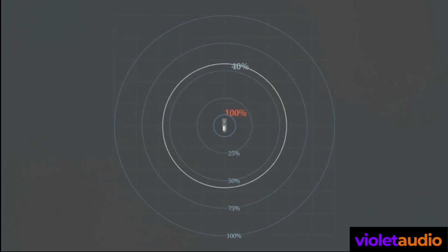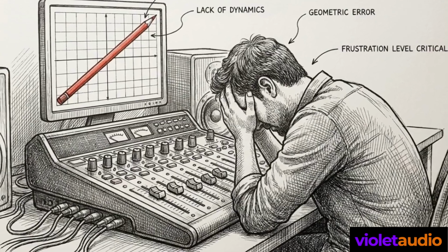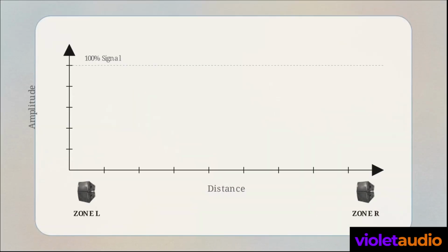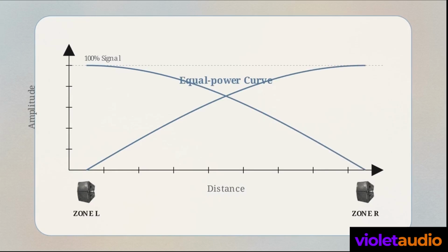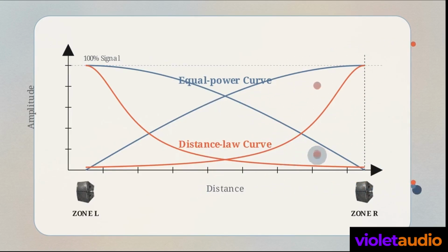Applying simple linear panning across a multi-zone immersive rig fails in practice. The acoustic transitions near boundary edges become too abrupt, destroying the illusion of physical space. Spatia relies on 2 spatial rendering formulas for signal amplitude. The equal power calculation ensures perceived musical loudness stays constant as a sound moves. Conversely, the distance law formula drops the signal off rapidly, preventing acoustic bleed into far-side speaker arrays.